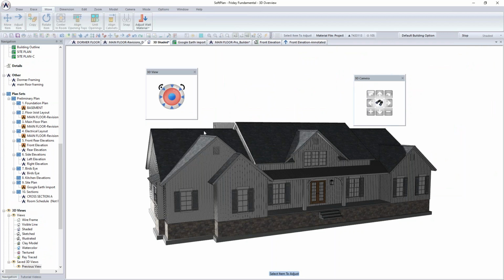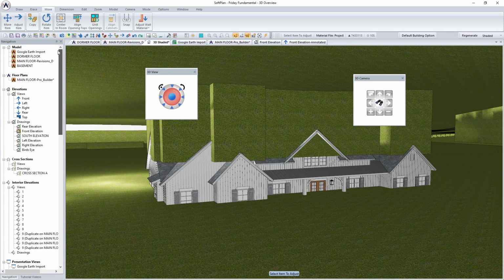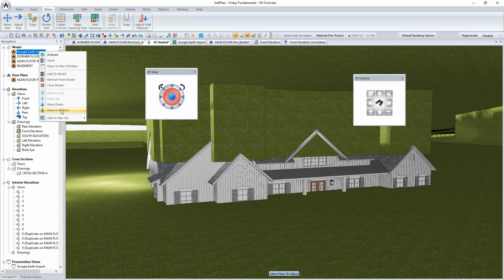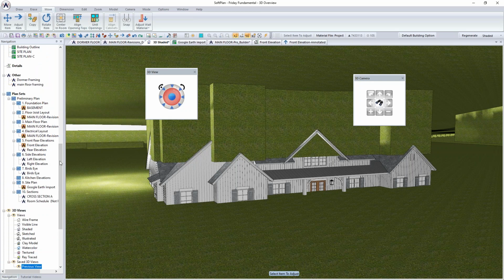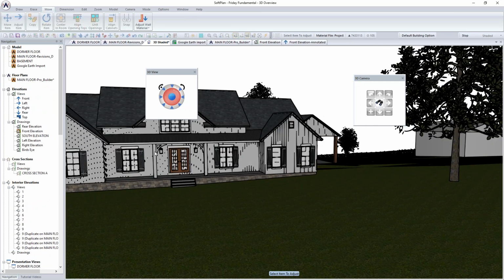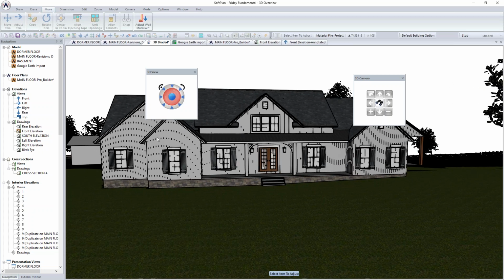And one of the things that you have to, I buried it in the house, is you always have to have the site on the bottom, okay? That may not seem important. If this is a 3D class, maybe you thought you were only going to learn about textures, but if you don't have the site plan on the bottom, then you can't get an accurate grade line as far as your model is concerned.